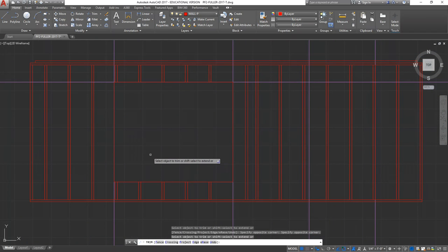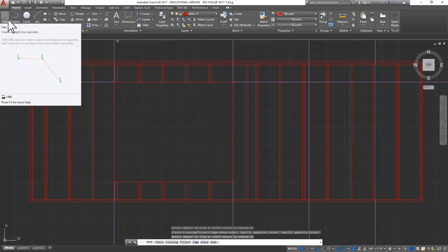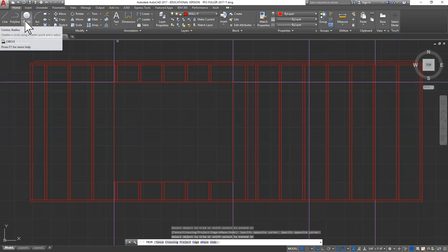Okay, so now what I need to do is make my header. I'm using 6-inch headers on my construction here. You can use 6, 8, or 12, it doesn't matter. Well, it does matter because the thicker, the stronger the house is going to be. But most houses only have 6-inch headers above the windows and doors.